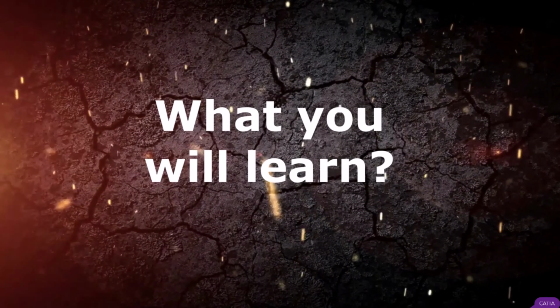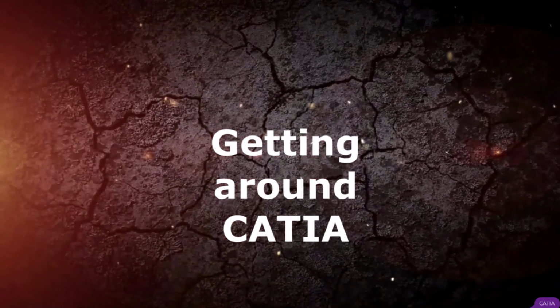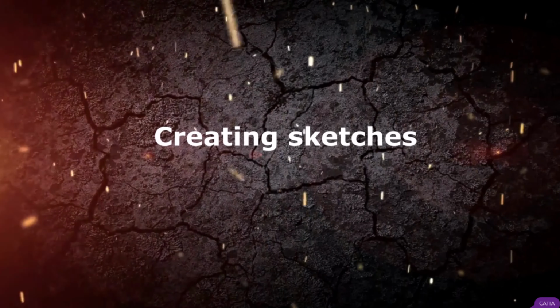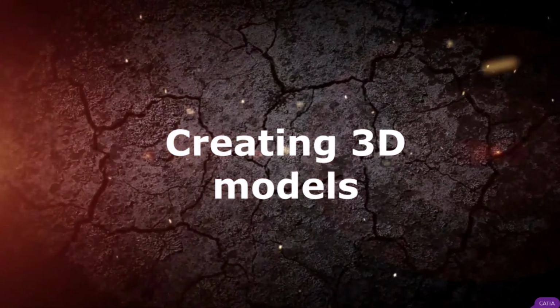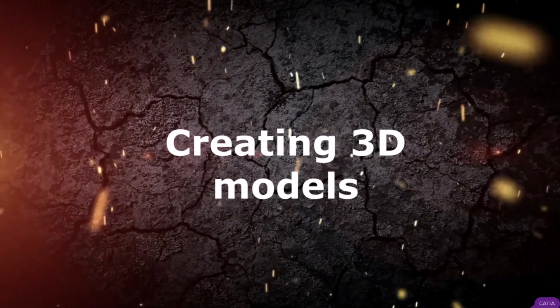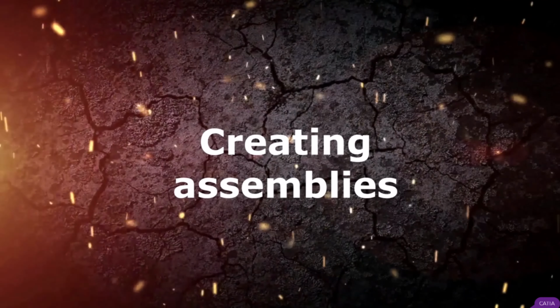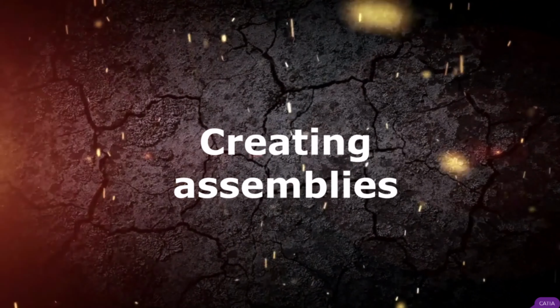What are you going to learn in this course? You will learn how to get around in the CATIA application and how to create a CATIA file. Then you will learn how to create a sketch, and we will explain all the sketch tools. Then how to use those sketches to create a 3D model. All main tools for creating 3D models will be explained. Then we're going to show how we can combine parts and create an assembly by using constraints.